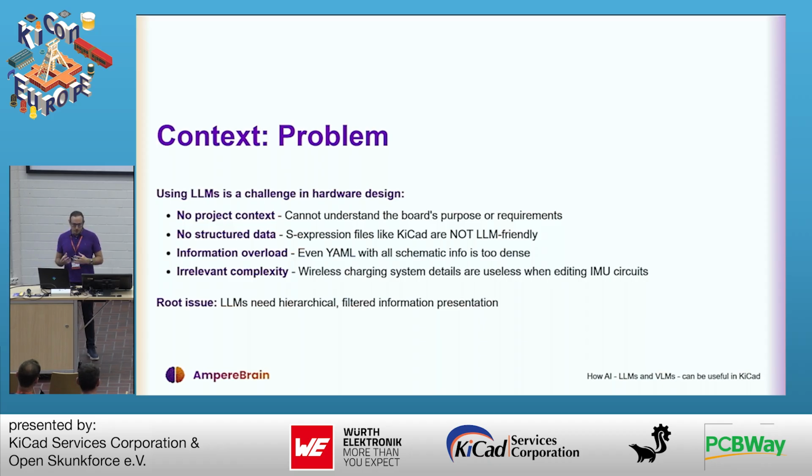Then it's about the structure of the data. KiCad uses S-expressions for its file format. It's not LLM friendly. It may be text-based, but there's not a lot of data out there that is actually expression-based, and LLMs get lost very, very quickly if you just feed them that type of data.